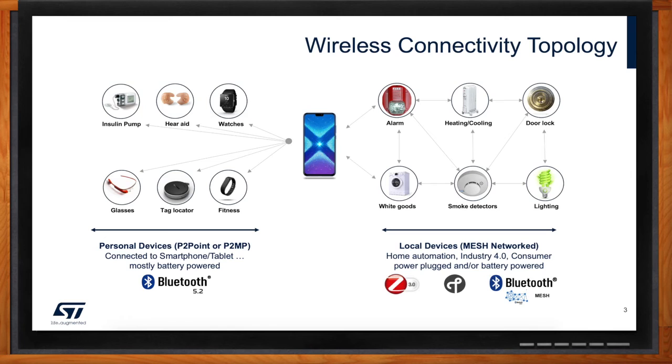And a second one in the second range, and here I'm more referencing other applications, that will use what we call a mesh network. It allows us to extend the reach. So here you can imagine many devices across a very wide area. If we are taking again the smart home as an example, we have a very large house. You could have, for instance, a backyard lighting system or even some window sensors, and each of them will serve as a relay for the next one, since they're going to extend the range, and some light or sensor won't be within reach of the gateway itself. So really those intermediate points will serve as a relay.